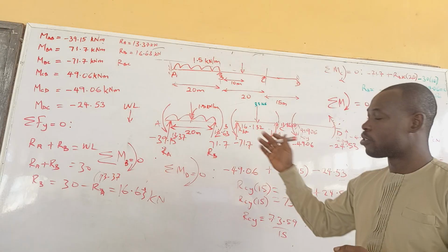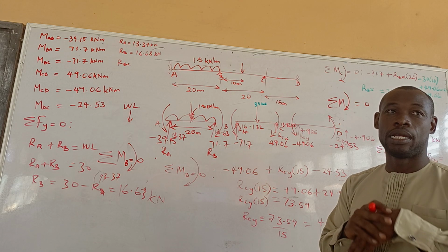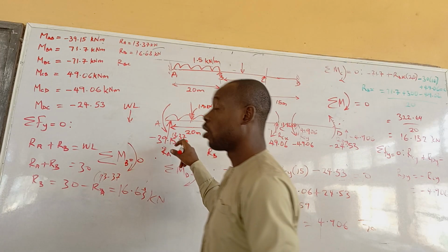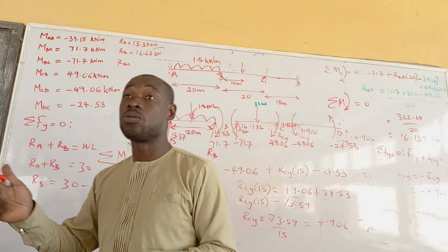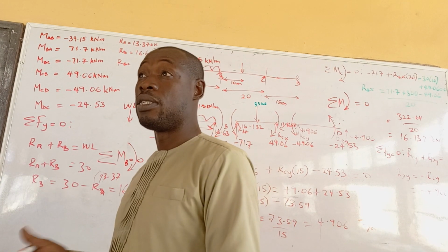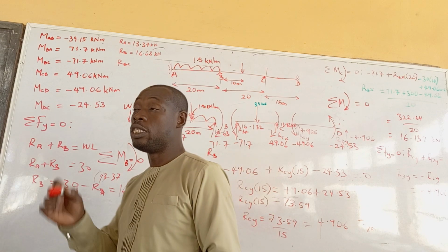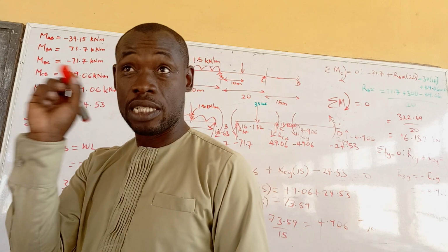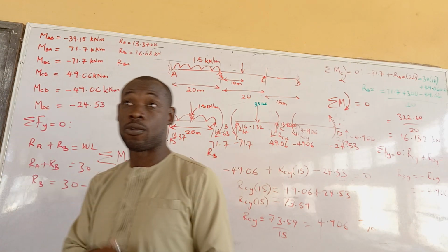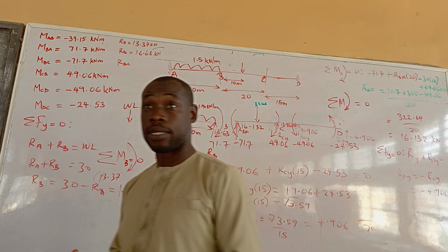I wanted to draw the shear force and the bending moment diagram before you came. I was telling them that all this calculation that we got is for us to be able to draw our shear force diagram, so that we will know the moment and the shear at each point, so that we know what we will provide for when we are doing our design.